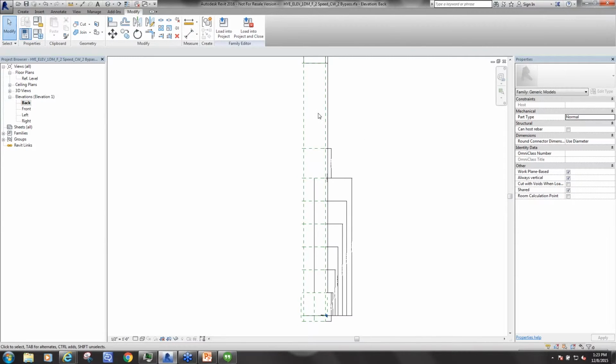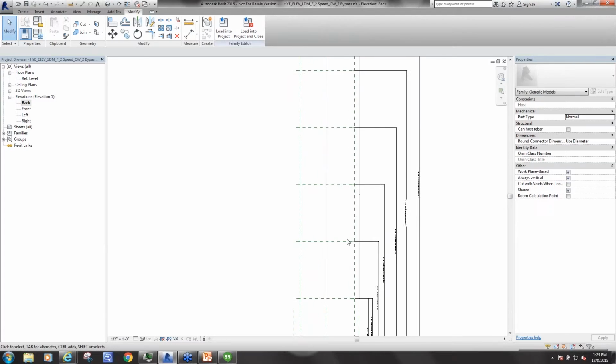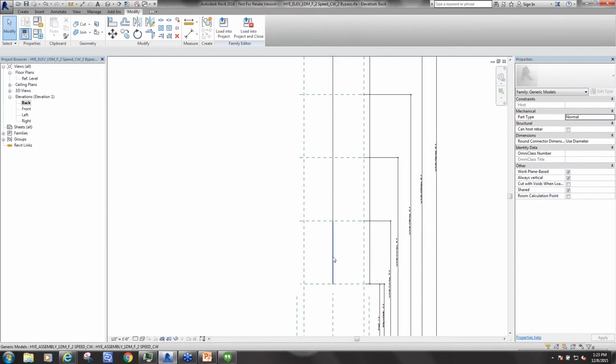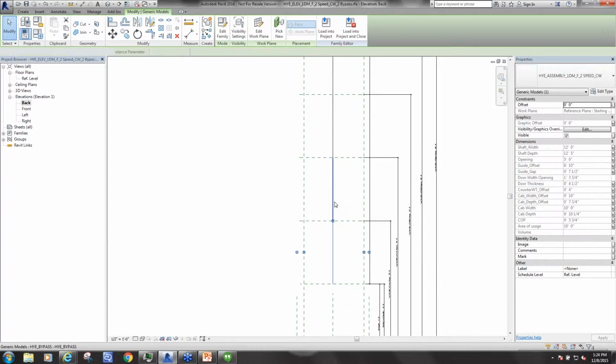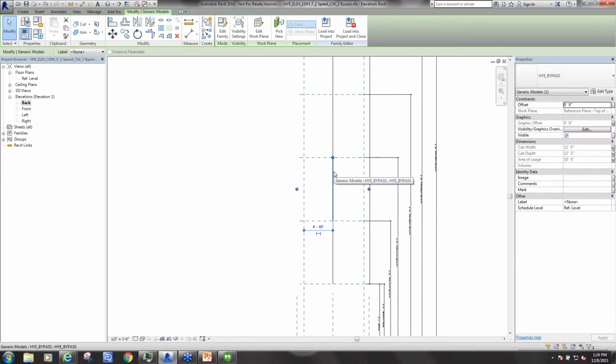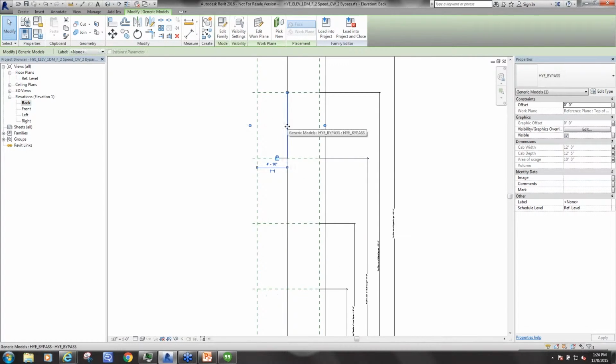So the elevator that we're currently looking at is a one-door middle front opening, 2-speed, counterweight in the back, 2-bypass elevator. So when you look at this in section, you're going to start to see that this is broken up here. An area of bypass merely means that it stops on level 1, bypasses 2, 3, and 4, stops on level 5, bypasses 6, 7, and 8, stops on level 10. So we have 2 areas where it's not an active cab.